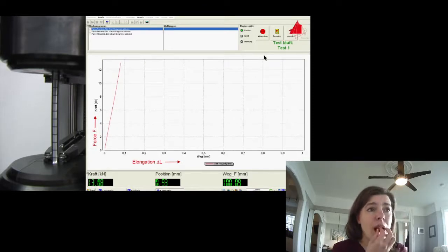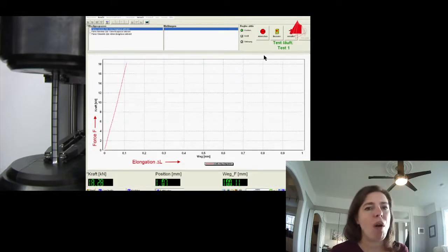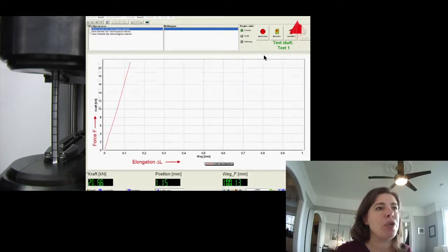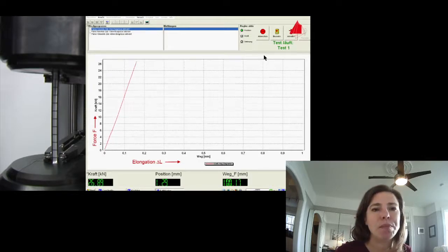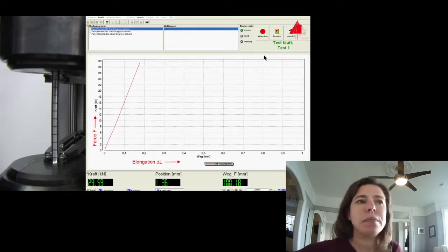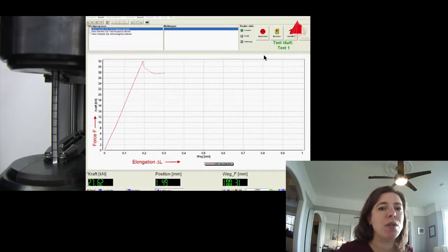Elastic zone. If the test piece were to be unloaded from this area, it would spring back completely to its original length. No residual strain. In materials with yield point phenomenon, the end of the elastic area can be seen clearly. The plastic deformation starts abruptly and is accompanied by a sudden drop of force.